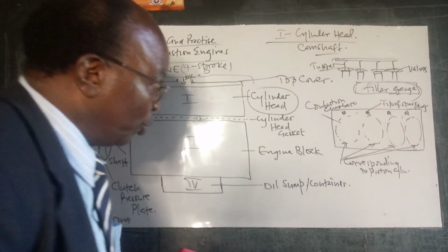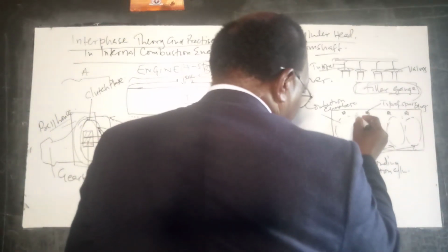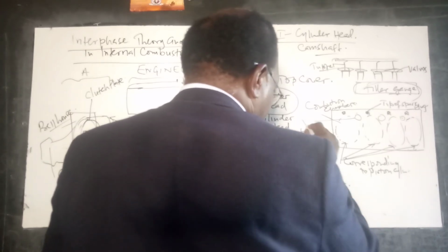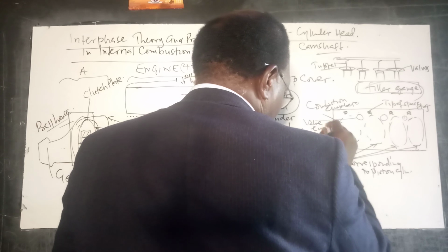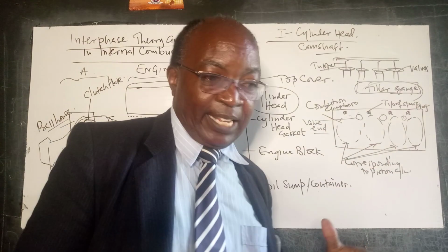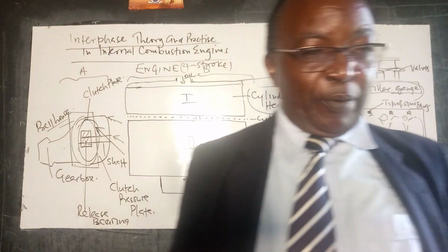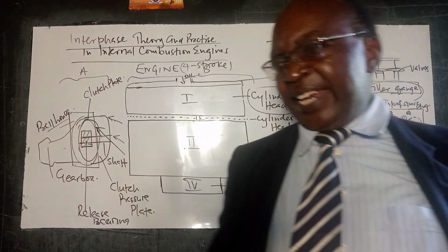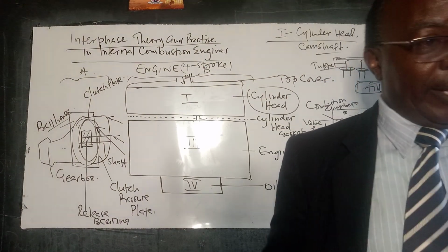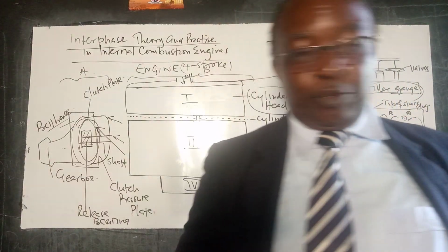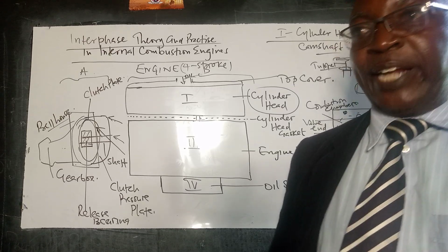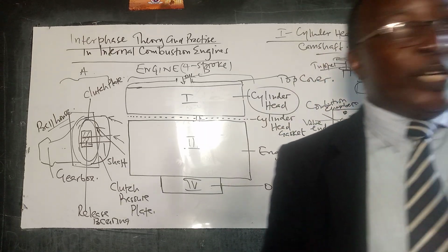And so also you are going to see the valve ends. Not very accurate, but you see the valve end, you do not see the stick. So these valves are on the cylinder head. And in most cases, when the engine has been run for quite some time so that it is due for overhaul, where you replace the worn out components and rebuild the engine, you'll find that the valves are quite sooty. So you need to grind them.